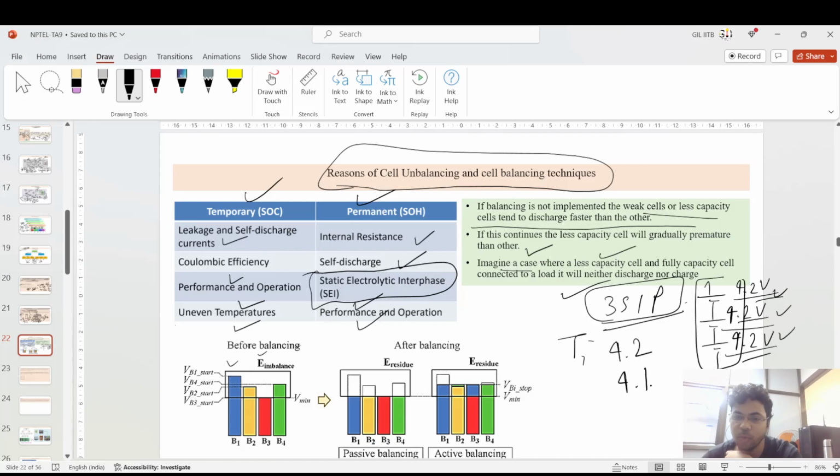So there are certain algorithms which say that if you have this 4.2 volt, and it goes 0.1 below to 4.1 or goes 0.3 above, then the balancing should be done. Balancing in what sense? If a cell goes from 4.2 to 4.3, it means that excess charge has been taken. So you should discharge this excess power to the 4.1 volt cell in the battery pack, so that you can maintain this 4.2 volt level for all the cells, for the actual utilization of the cells.